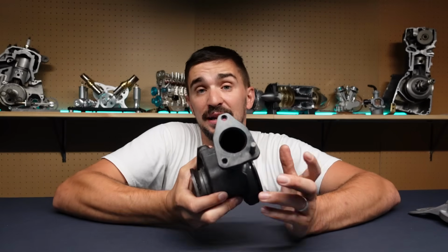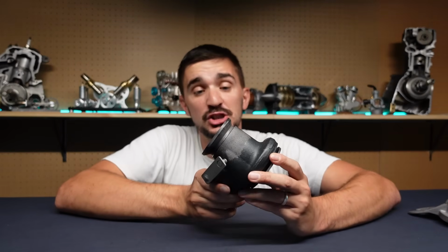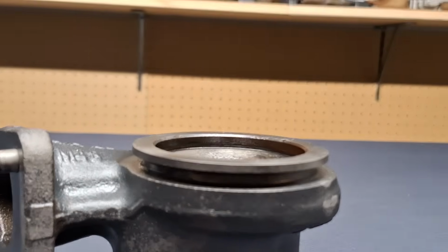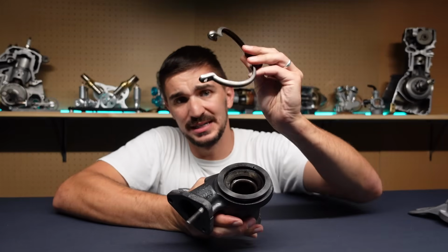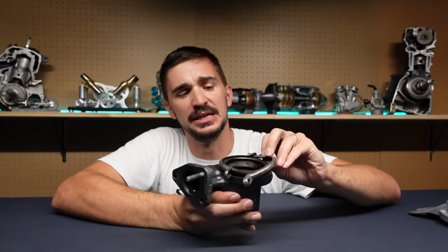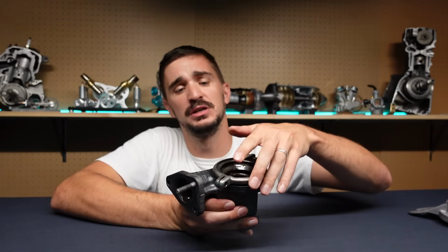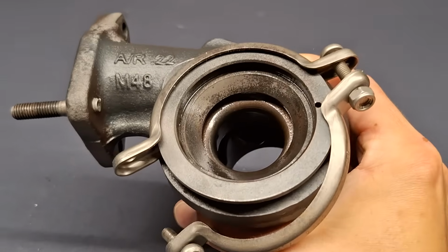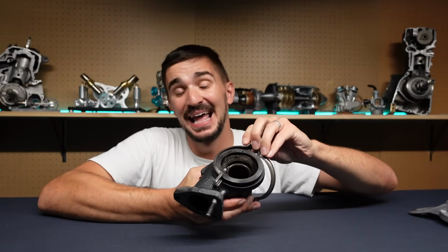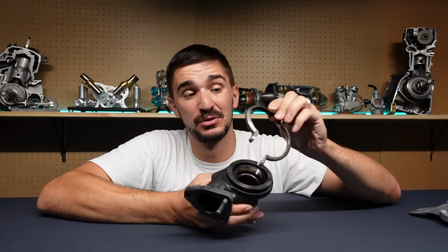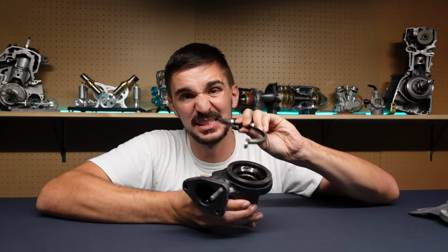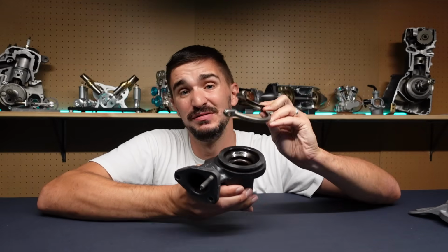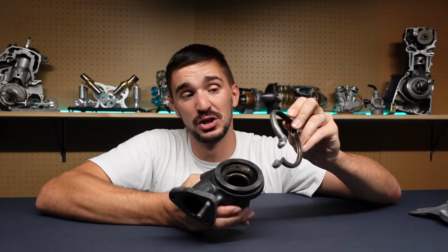Something that can be considered an improvement, which we can see on this turbo on both the downpipe and the connection to the center housing, is a V-band connection. Now this one is with 2 bolts. It's not what you're typically going to see on aftermarket applications. For example, it's usually going to be just 1 bolt, but it's an improvement because number 1, it saves space. It allows a more compact connection. And number 2, this is less susceptible to the bolts rusting and becoming seized and impossible to remove. So it's usually easier and faster to remove the turbo because there's less bolts.